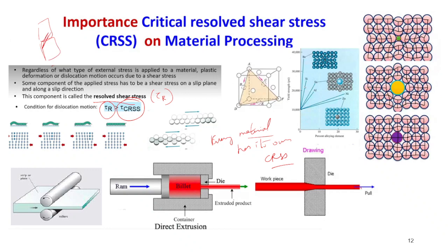The deformation will usually be at a 45-degree angle, and it will always be along the slip plane, and specifically in the slip direction in that particular slip plane. Here you can also see how the dislocation is occurring as the tensile force keeps being applied.